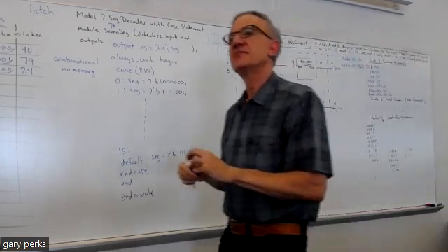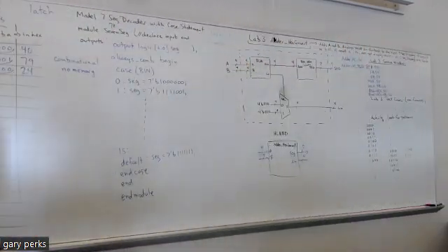Why is AN 4-bit? The reason why AN is 4 bits is because there are 4 7-segment displays on your Basys board. So each display has an AN. So for example, when you're looking at the Basys board, if the switches are on the bottom, the furthest to the right 7-segment display, that's your 0th display.